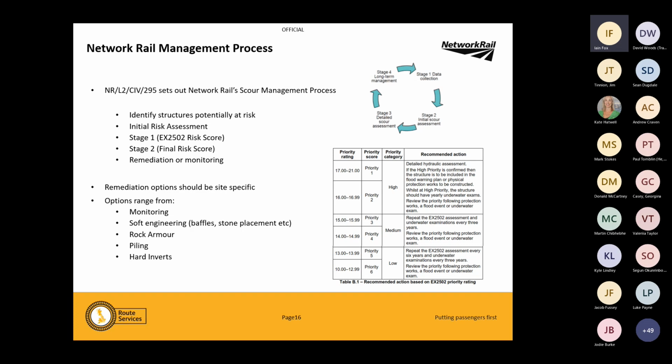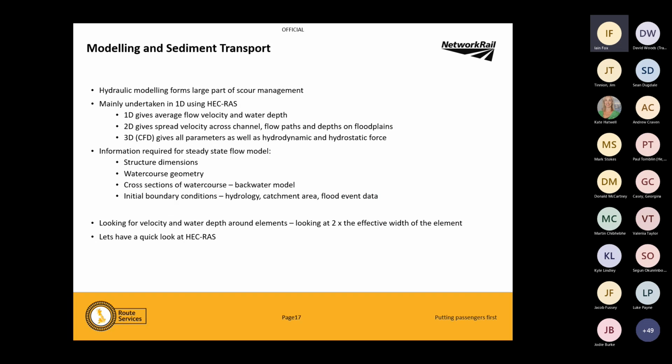The remediation options: monitoring, could be some engineering works. There's a myriad of things that we can do to actually mitigate scour. We do some modelling, so there's some hydraulic modelling going in. It's not particularly in-depth or extensive hydraulic modelling, because all we really need to know is the flow direction and the velocity. And we need the velocity at the base, the bed, because that's where the scour happens.